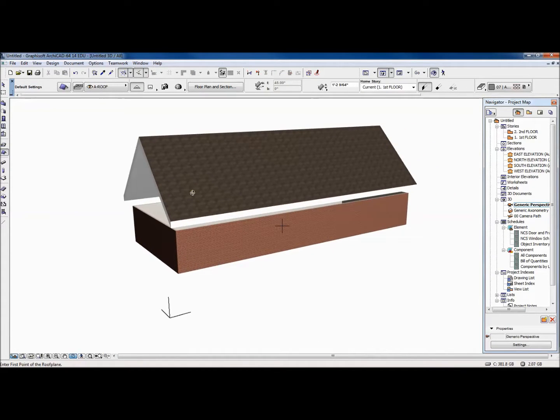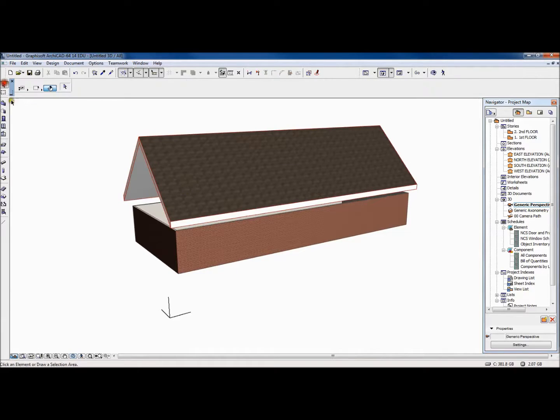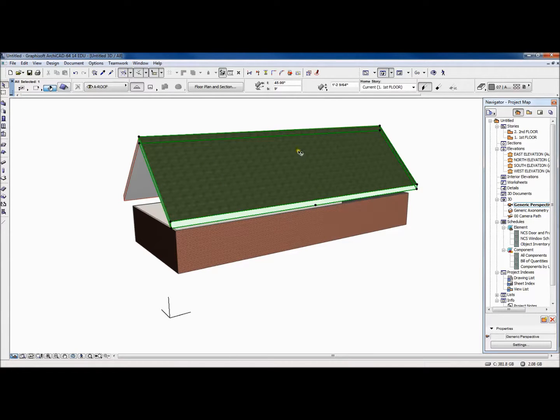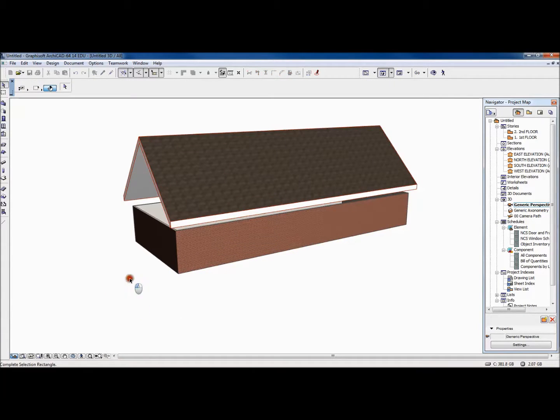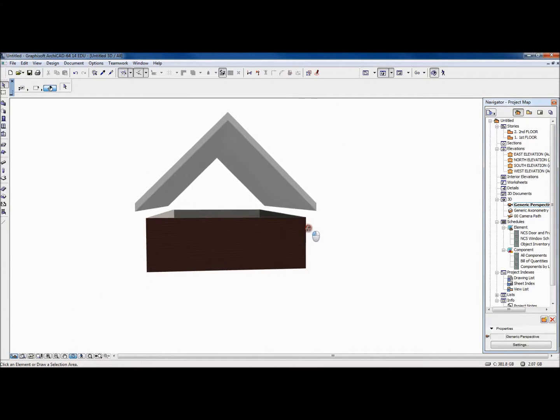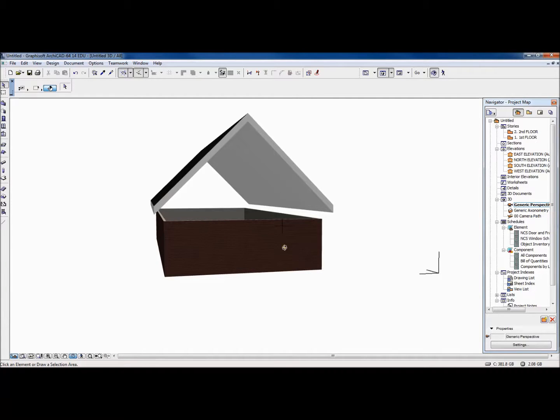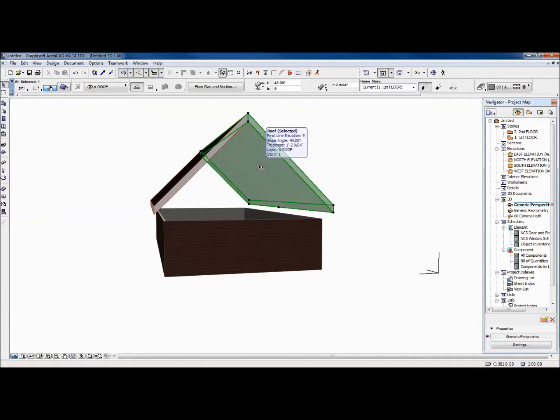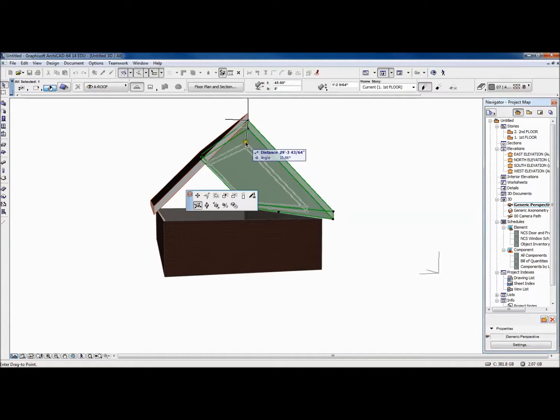Now, this particular roof, if we look at this section, this particular section of the roof is set at 9 feet, and that's not correct. If you look at this section right here, we need to actually drop that roof down so that it sets on the walls. And so once again, if I pick up this tool and select this roof section, I can set the elevation of that roof section at 8 feet, and it drops it down. A couple different ways that this could be done.